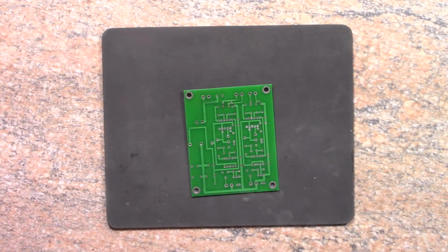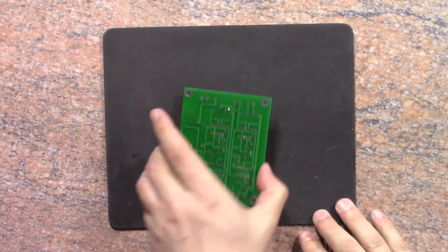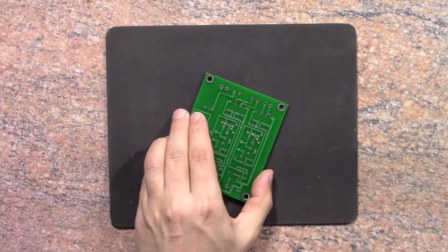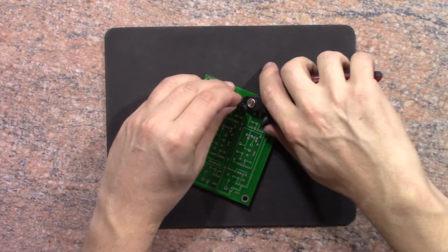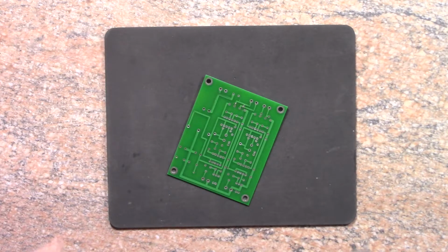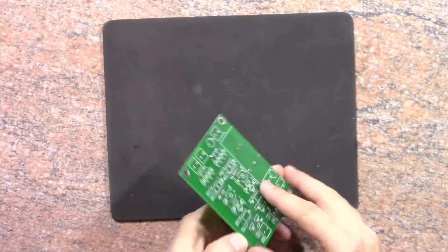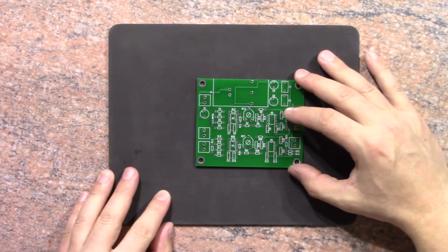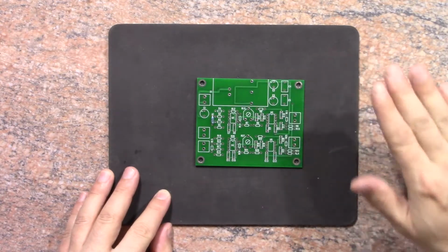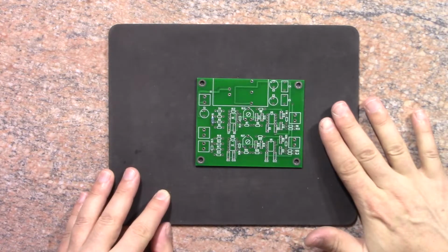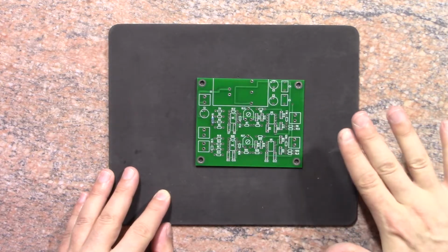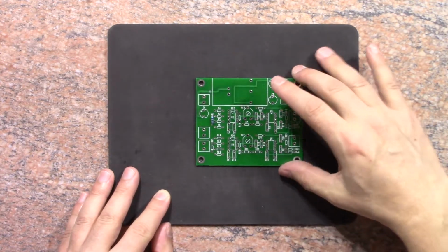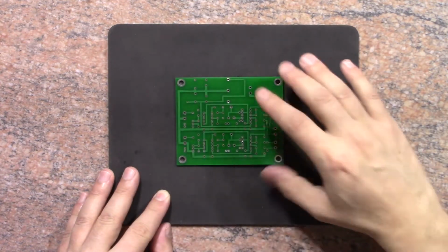So that's it, components soldered onto the board, nice and neat. And now the extra pins or the longer pins can be cut off, and that's how you solder the components. So you always start from the lowest profile component on the board and then build it up to the highest components. Turn the board upside down and solder it from the other side.